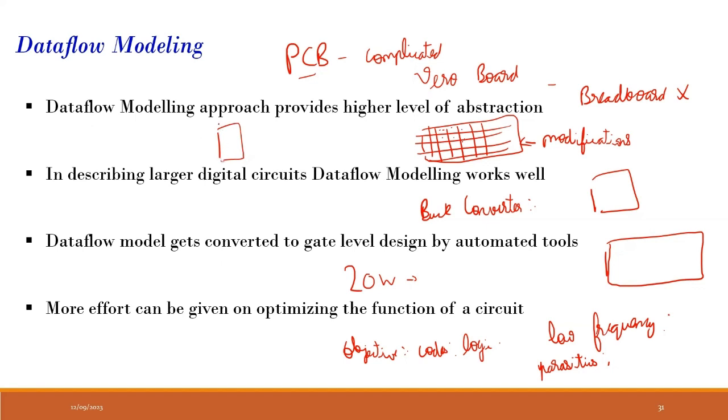Those ICs we're talking about, so ICs you can also solder to the board. There also comes the IC holder, so you can solder the IC holder and then put the IC on top of that. But that you'll have to check. That may not be possible for all ICs.